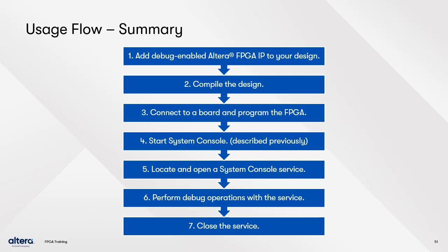You then will need to find the service. This is done using the System Console commands. After locating your service, it's convenient to set a variable equal to it. Once the service is found, you can open the service using the variable defined in the previous step to perform debug operations with the service. When done, you can close the service.